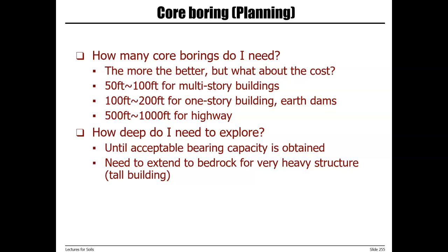With respect to the depth, the boring continues until acceptable bearing capacity is obtained. Again, for larger structures with a heavier load, we need to extend or continue the boring until we reach the bedrock.